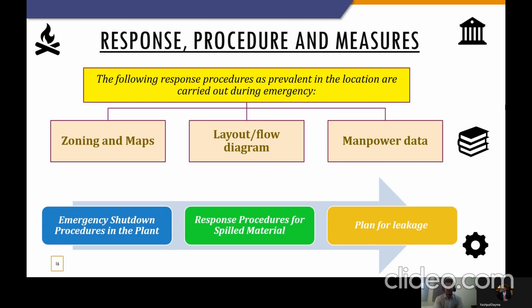Coming toward leakage, this is a very basic or general accident taking place in any industry or any part of the installation. The care to be taken is that we should first have the knowledge of sprinkling water on the outer surface of the tanks so that the temperature does not rise. Otherwise, if the temperature rises to the highest level, the tank or vessel would burst. Vessels, buckets and fire extinguishers should be there, and training on how to operate them should be given to different people.